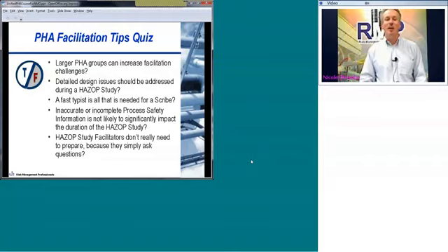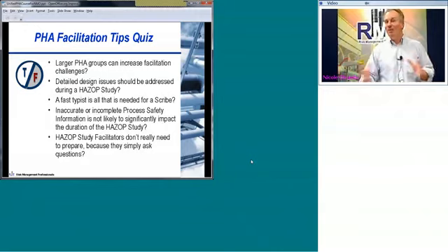When you're constantly having to rethink or ask questions about missing design information, and I've done HAZOP studies where I've got the P&IDs, I'm properly prepared, I understand what's on the P&IDs, and then I start asking questions about what can go wrong, and I'm talking to the group and I'm getting these blank stares at me, and then after about 5 or 10 minutes they say, oh, we removed that equipment, or oh, there's an extra pump there, or it can be totally different from what's on that P&ID. So you can waste a lot of time with inaccurate P&IDs.